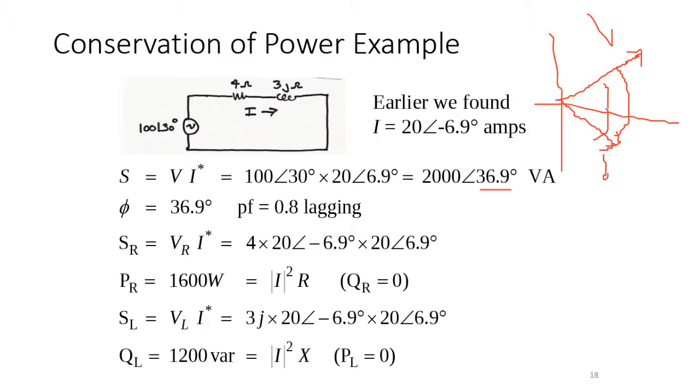Okay, the power factor is lagging. Why will it be lagging? Either you look at the circuit, the network here. This is inductance. It's not capacitance. Therefore, the power factor must be lagging. So when you say 36.9, the power factor is lagging. Current is lagging the voltage.